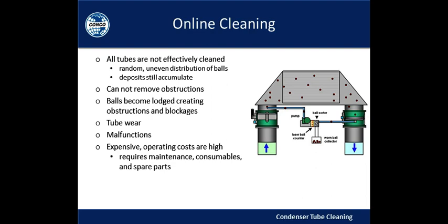If you have obstructions, sticks, sea life, leaves, cooling tower fill inside the condenser, then it's unlikely that the balls will go through the tubes at all. If they do go through the tubes, they may become lodged. When they're lodged, no cooling water is going through the tube at all. No flow, no heat transfer, less heat transfer surface area, and then the condenser performance begins to erode.